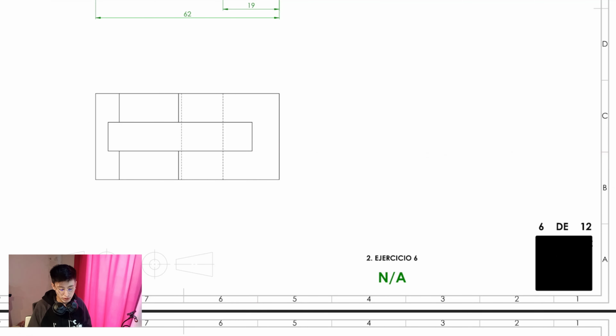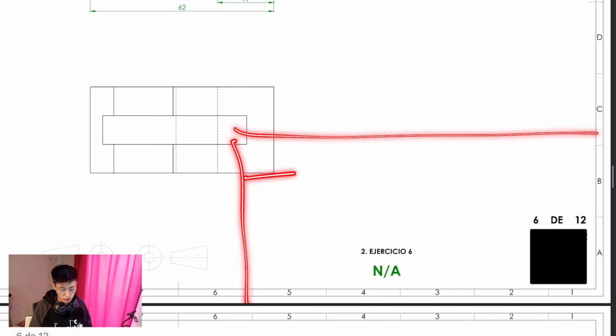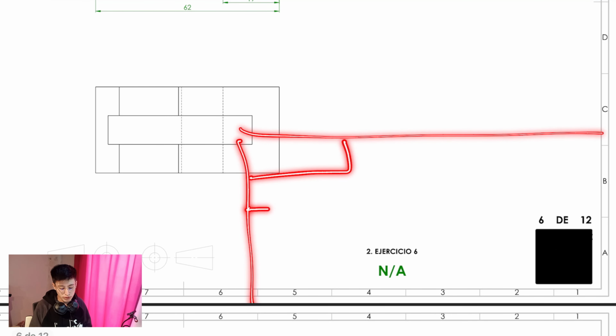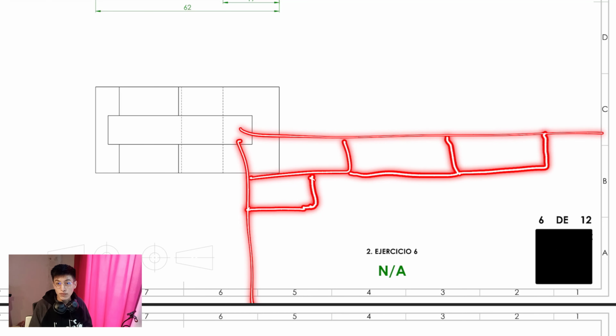It is usually right here, in which you place your name, the person who is checking your work if it's necessary, which could be your boss, the material of the part if it's been manufactured, and some tolerances information, if it's been processed through a CNC machine, so the technician has to verify the tolerances and verify that it is meeting the requirements of the part.